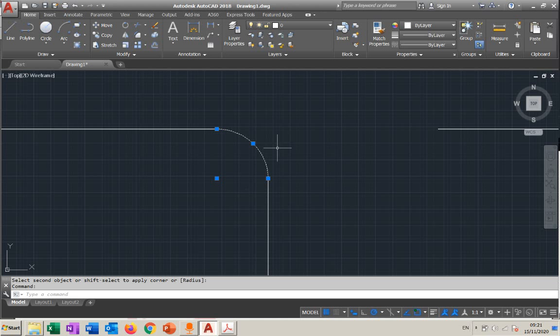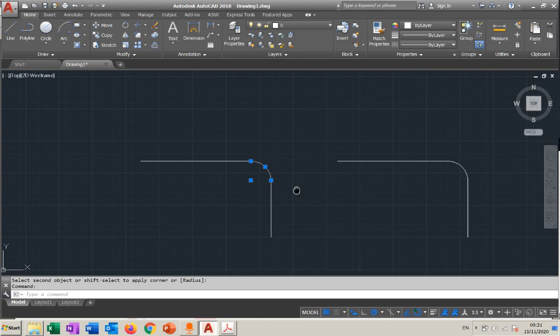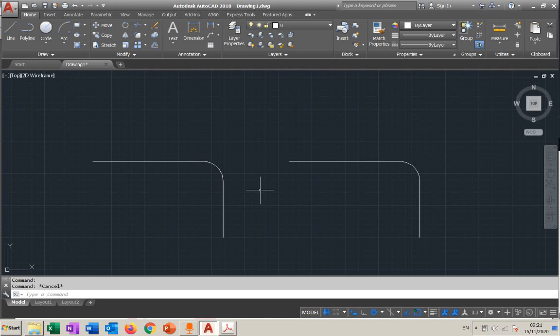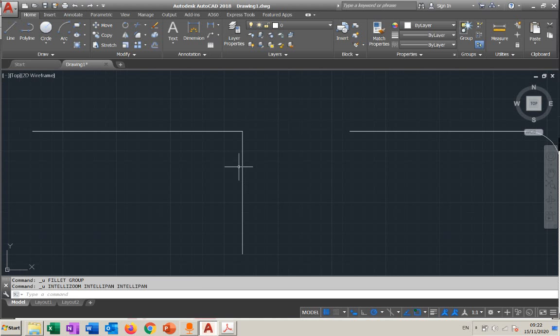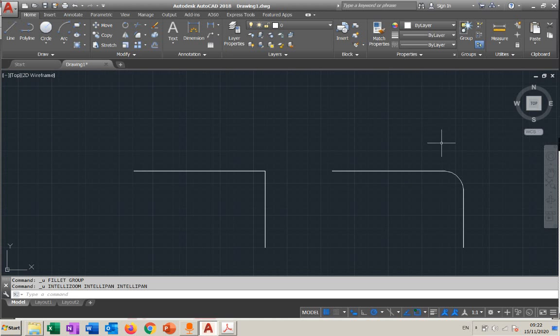It even deleted these two small parts for me. So the shapes that you have in the model, whenever you see a round corner, imagine it was a sharp corner before, then fillet can be used to convert it to the round corner.